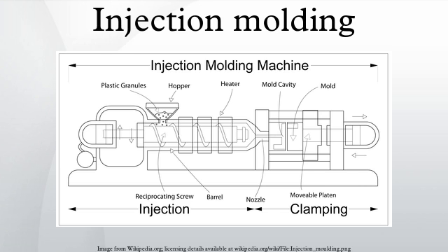A mold can produce several copies of the same parts in a single shot. The number of impressions in the mold of that part is often incorrectly referred to as cavitation. A tool with one impression will often be called a single impression, cavity, mold. A mold with 2 or more cavities of the same parts will likely be referred to as a multiple impression mold. Some extremely high production volume molds can have over 128 cavities.